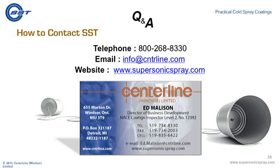Certainly, starting with a standard metal, there's a world of additives out there that we can use to help increase adhesion to substrate. It's fairly specific depending on what type of coating and what type of performance you're looking for, but that's generally how we go about making adhesion, and we've already got a database of hundreds of combinations of coating substrate from which we can start.